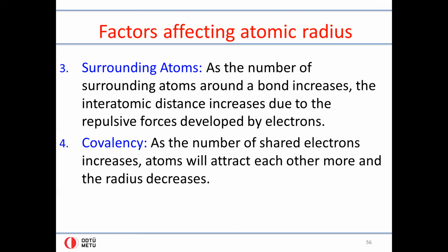When you have only on one side of an atom another atom, the ability to pull or push that neighboring atom will be different than if you have two neighbors on either side. So then, depending on the overall arrangement of atoms in a material, the atomic radius, hence the resulting bond length, hence the resulting strength of the bond, or the energy needed to break this bond, will be affected.